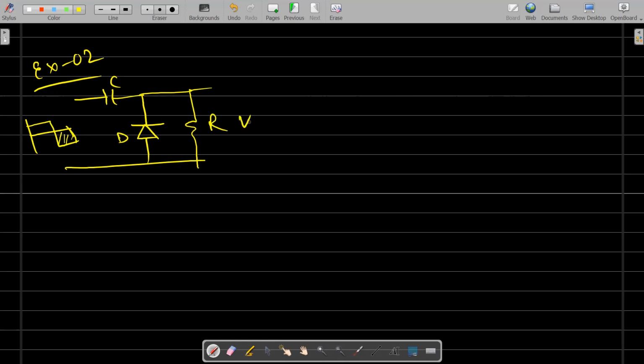Because in the operation of the clamper circuit, the output voltage depends upon the voltage across the capacitor. The amount of shifting in DC level or DC voltage you are getting is due to the capacitor. So your first job is to charge the capacitor, and so you have to start the analysis from that cycle where the capacitor will be charged, that is the negative cycle in this case. Okay. And since it is a periodic waveform, the cycles will be repeated. So if you start your analysis from the negative cycle, then you can do it for the next positive cycle. What will happen? The same value will be here. Yes, for time t equal to 0, the waveform will be a little bit different, but after that the same repetitive waveform will be there in the output.